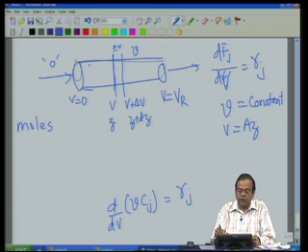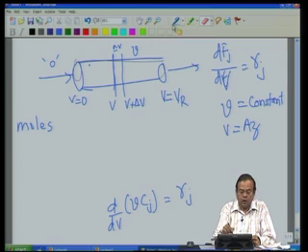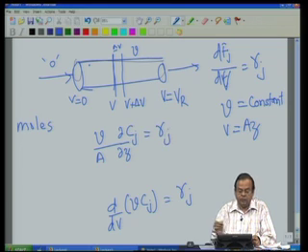So, this is A into Z. So, if that is the case, then we can simplify this mass balance equation further. What is that simplification? The volumetric flow rate is constant, so we can take it out of this mass balance equation, common outside. So, we have V, and instead of dV we will put A ∂z of Cj equal to Rj.